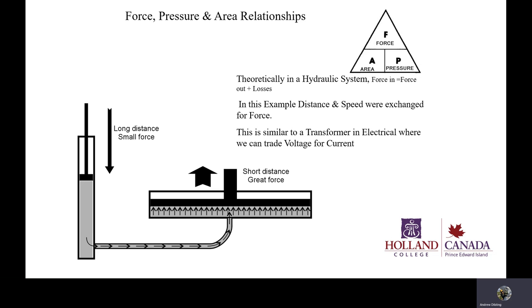That's the same kind of system that you have here. And that's basically a system at rest. The fluid is being worked on by either the pump or a bypass valve, which returns the fluid back to the chamber to repump it when you want to reset the jack.